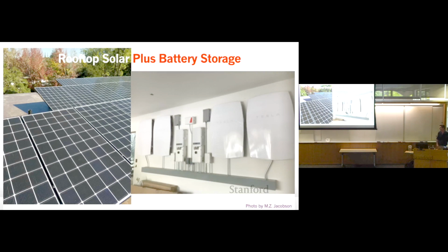So it has solar on the roof, about 13.6 kilowatts. And there are batteries in the garage, each one is 3.3 kilowatts. And there's about 2 hours of storage at full discharge rate, so 6.6 kilowatt hours. And you can multiply by 4 to get the total.